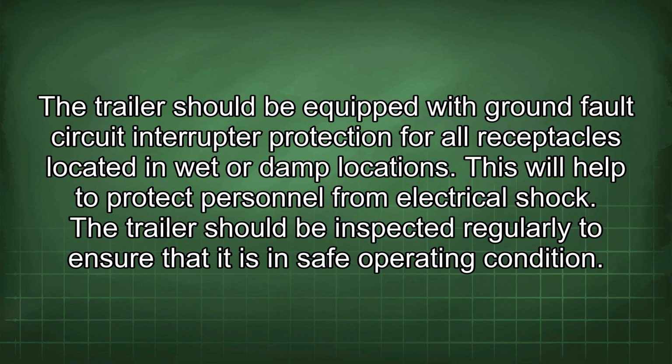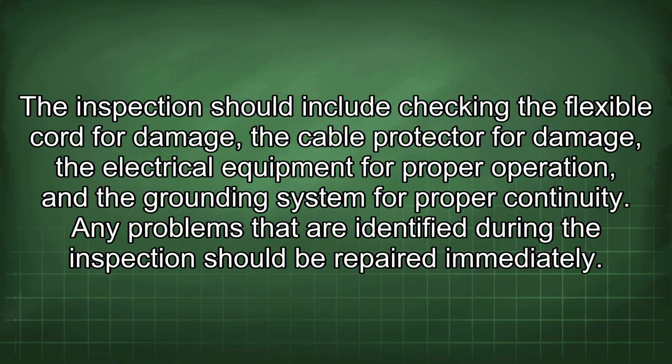The trailer should be inspected regularly to ensure that it is in safe operating condition. The inspection should include checking the flexible cord for damage, the cable protector for damage, the electrical equipment for proper operation, and the grounding system for proper continuity. Any problems that are identified during the inspection should be repaired immediately.